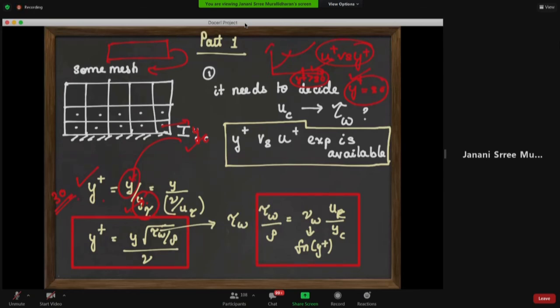So what did we talk about U tau? Y plus is Y times U tau divided by kinematic viscosity, which we do know for the fluid. Now, what was U tau? If you remember, I'll just carry this to the numerator. That's what's here. And you know U tau is the square root of tau wall by rho. Are we all okay till this point?